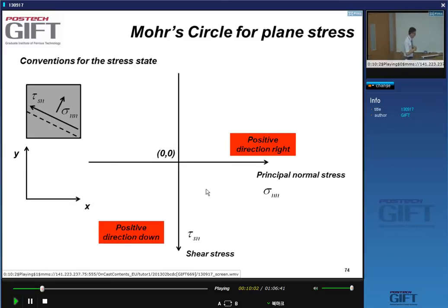That's one thing. And then the second thing is that once I have my Mohr circle for a specific stress condition, I can, of course, find not only my stress situation on the faces of a small cube in the material with this orientation, but for any other orientation.